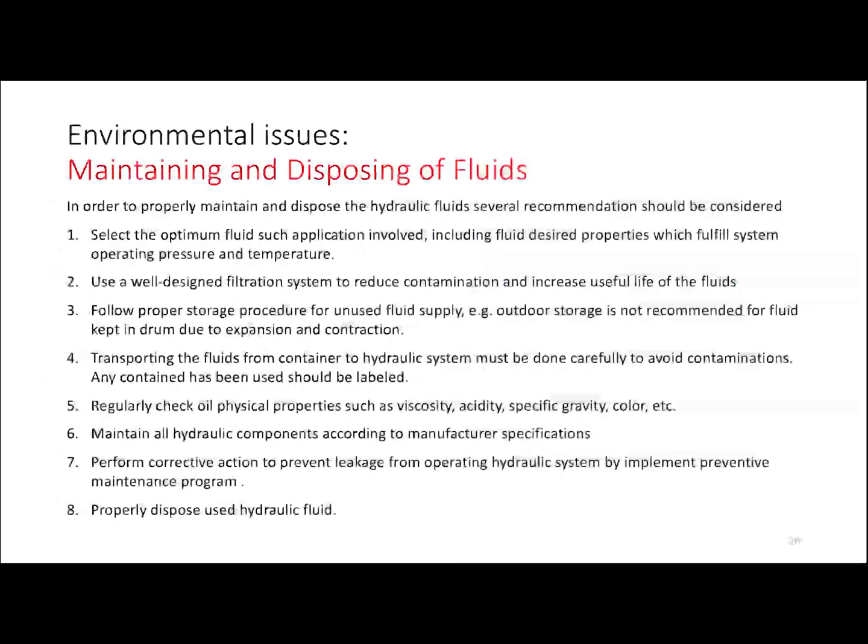Okay, in maintaining and disposing of fluids, several recommendations should be considered. First, select the optimum fluid for the application involved, including desired fluid properties, which will fulfill the system operating pressure and temperature. Second, use a well-designed filtration system to reduce contamination and increase the useful lifetime of the fluids.